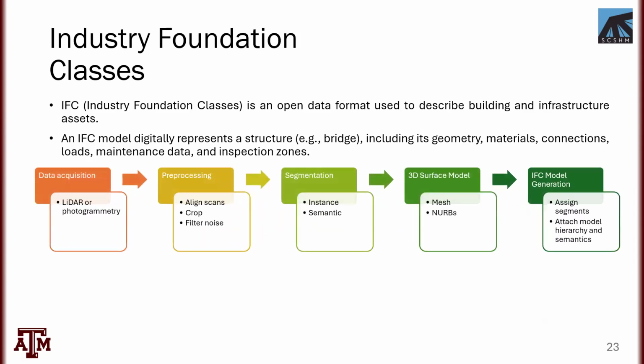So here is the pipeline for an industry foundation class. You basically have to follow through all these steps: data acquisition, pre-processing, segmentation, 3D surface modeling, and finally, you generate your IFC model.